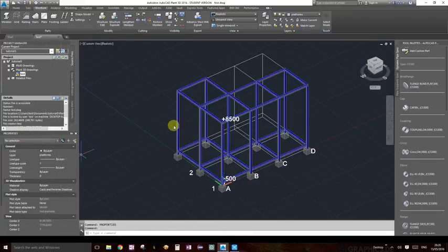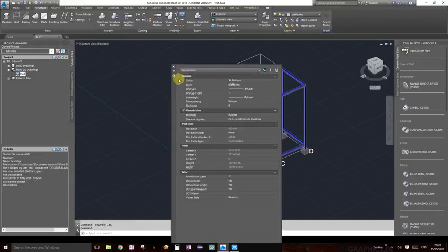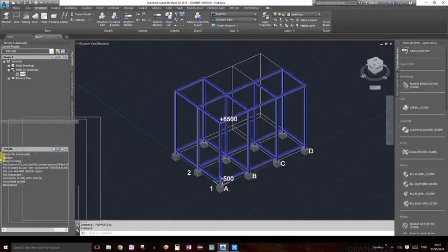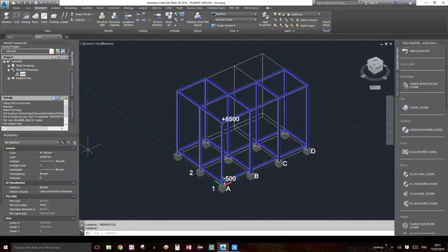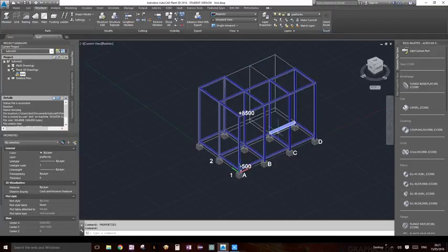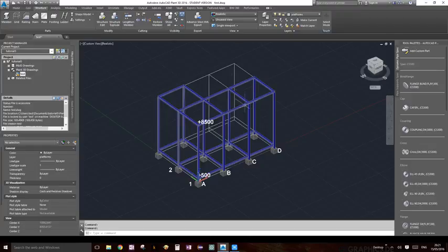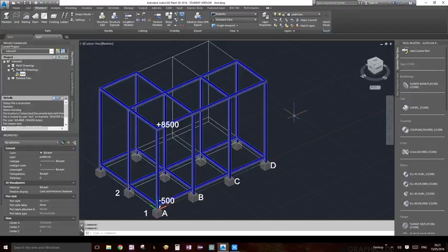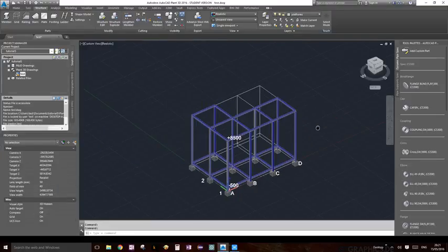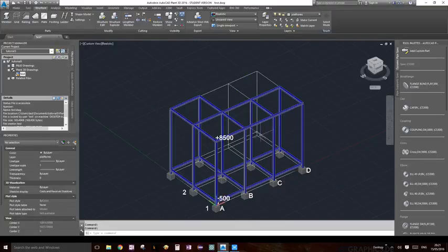Now usually it's gonna show up like so, a big window in the middle of nowhere. So what you can do, just drag it and kinda dock it right beneath your project manager window, and that works just fine. Okay, so let's get started. So the first thing I'm going to show you guys is how to show only selected objects in the AutoCAD Plant 3D environment.